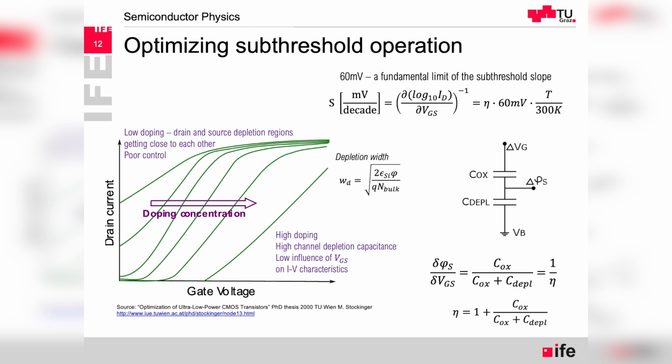So there are two parameters to play with. One, as a person who can select from different transistors available in the process, or a process engineer, or the whole team of engineers, is tuning the doping. And another thing is that we can also change the body bias voltage. Everything comes down to the structure of two series capacitors: we have the gate oxide capacitor and the depletion capacitor.